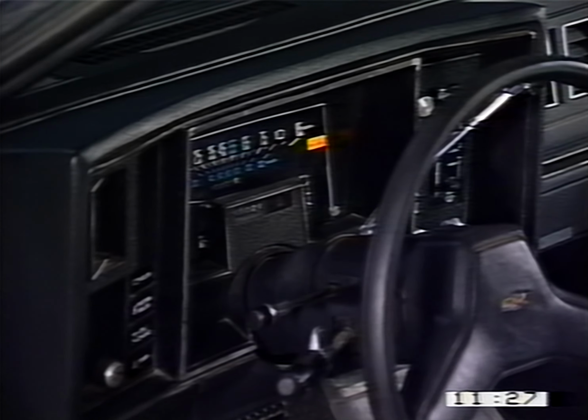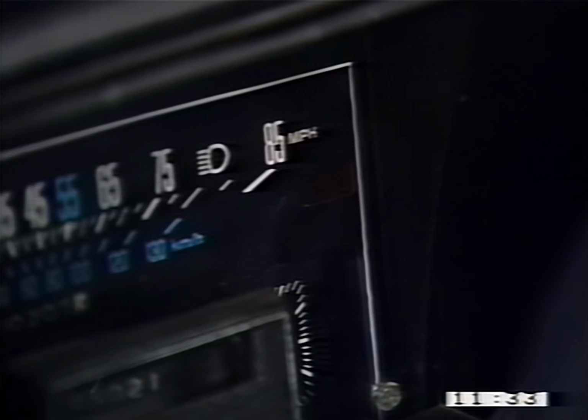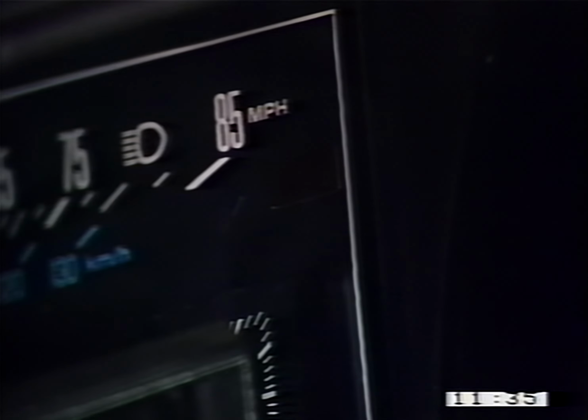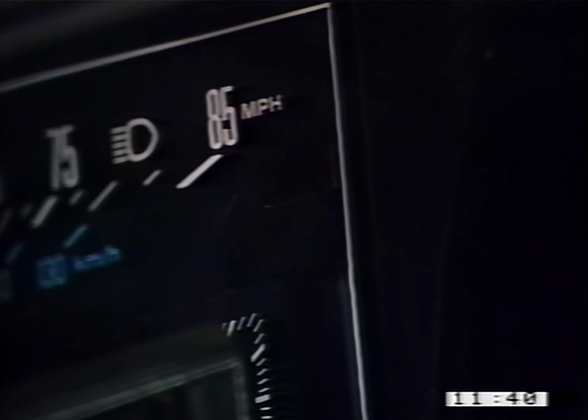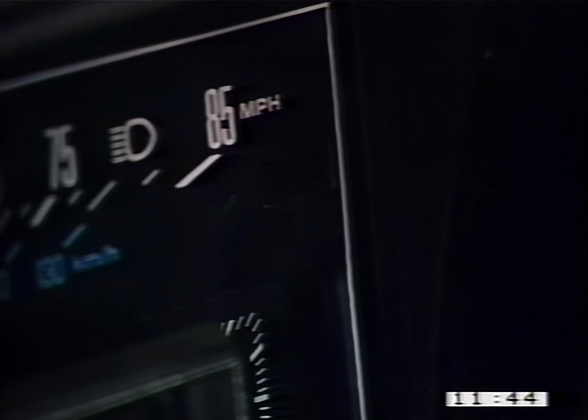The monitoring of fuel ratio on fuel-injected vehicles in field service mode is used to determine a lazy or damaged fuel delivery system. If the fuel delivery system is operating correctly, the check engine lamp will flash on and off every 2 to 3 seconds. This indicates that the ECM is constantly correcting minor differences in fuel delivery.